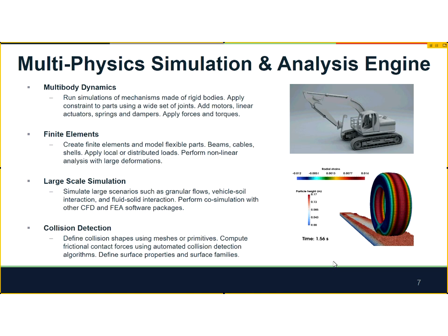And then finally, a big part of this is, they're interested in connecting pipes together and collisions underground. And so the collision models, the collision detection and handling of when you collide two pipes together, screw them together, applying large torque to make up a joint, the physics of that operation is critical. And so we're using collision detection from this tool to be able to model that.